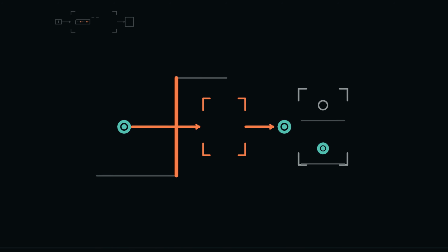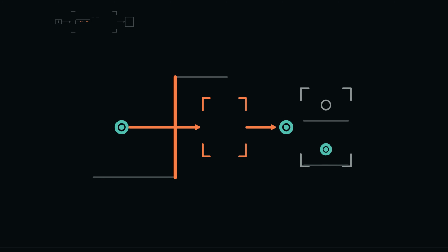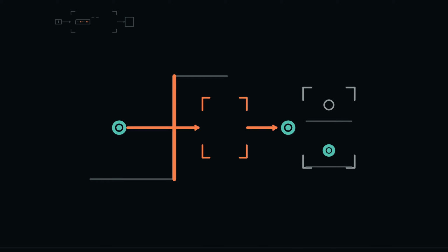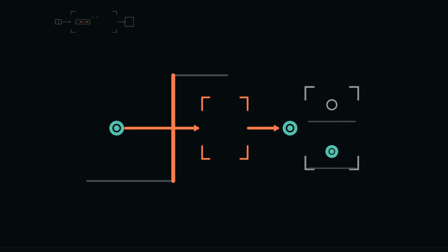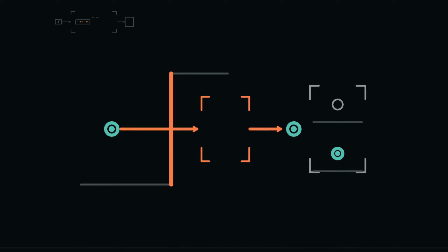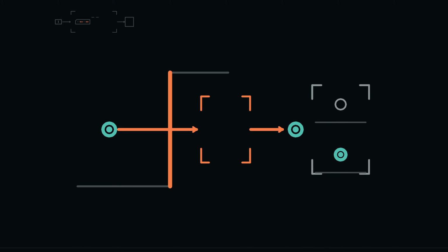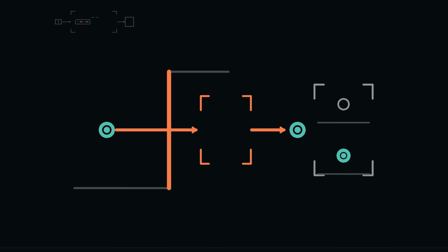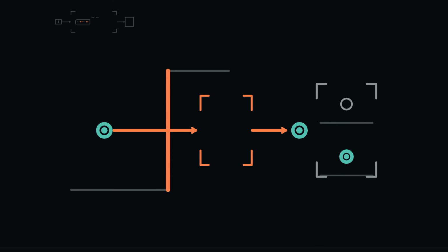After the first edge, change D back to 0 halfway through the cycle. Predict Q. It remains 1 because no active edge has occurred. The new input value may travel through the combinational route leading to D, but it has not yet become stored state. At the second rising edge, 0 is captured. After delay, Q becomes 0.